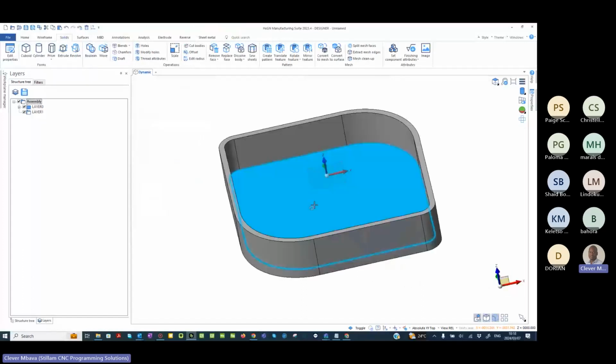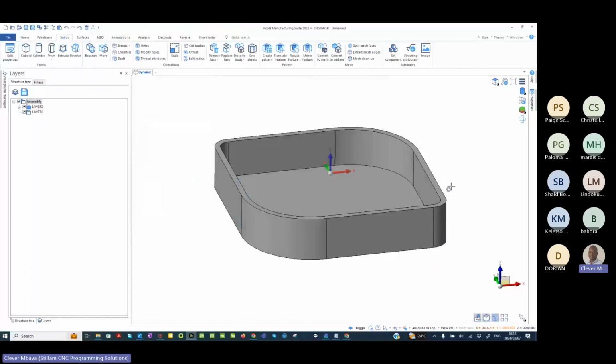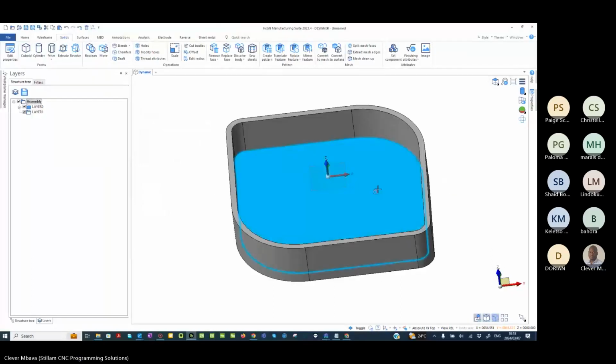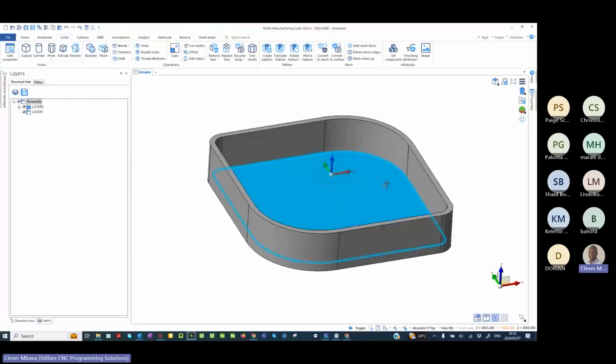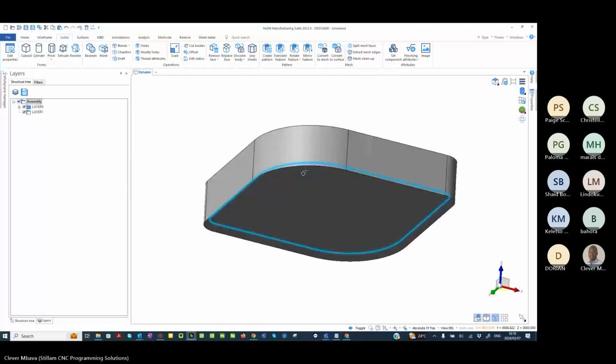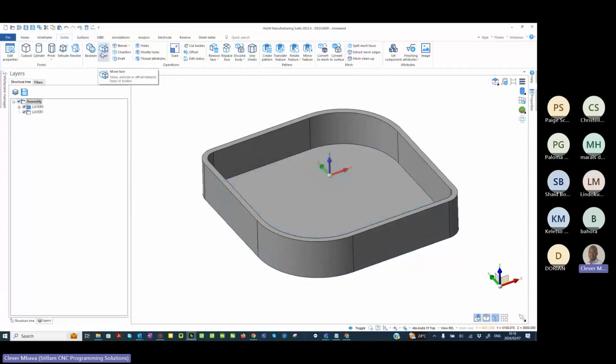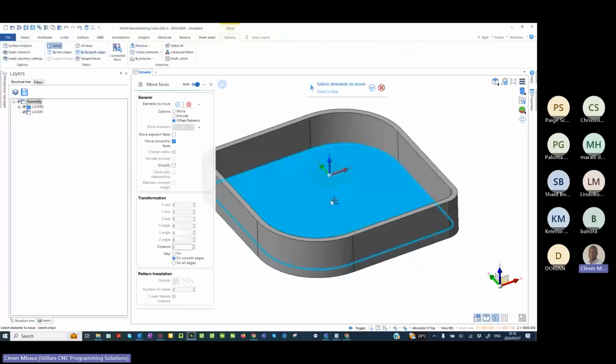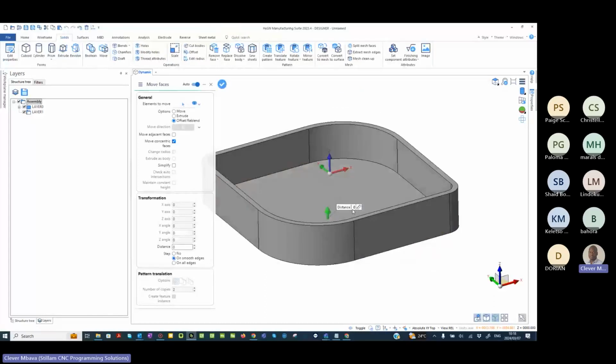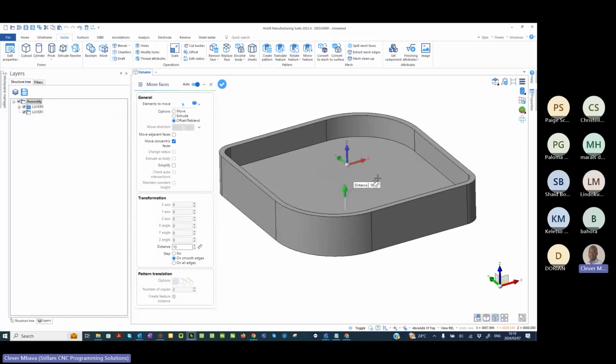All right, from there, I would like to raise this bottom face halfway, the thickness of this part. I know at the moment I've got 4 millimeter from the bottom here. So I can go and say move. I pick up the face that I want, and you can see there, I can pull it like that. I can either just type the distance that I want to use. Right here, you can see it's changing as I'm pulling this up. We've got so many features to use.